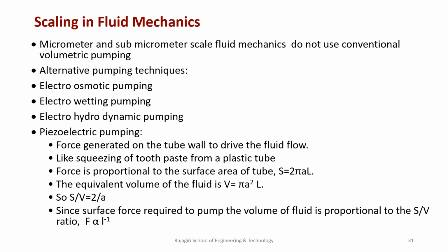In piezoelectric pumping, force is generated on the tube wall to drive the fluid flow. It is similar to squeezing toothpaste from a plastic tube. So the force will be proportional to the surface area of the tube, S, which is equal to 2 pi into A into L. A is the radius and L is the length of the tube. The equivalent volume of the fluid will be V is equal to pi A square into L.